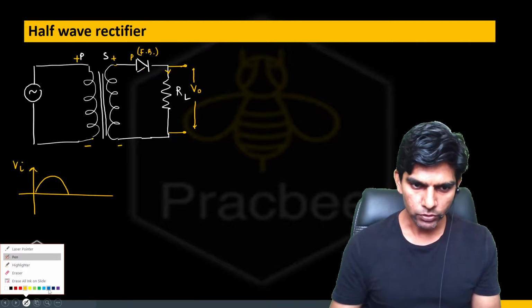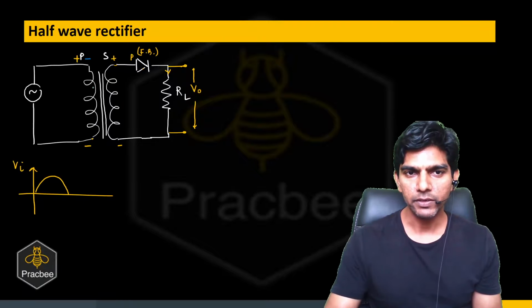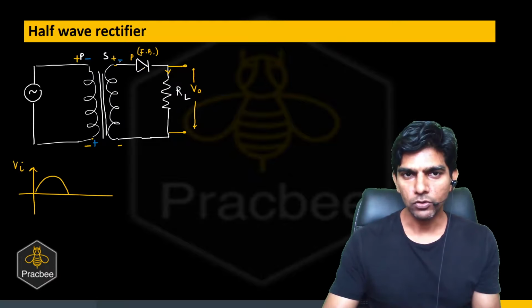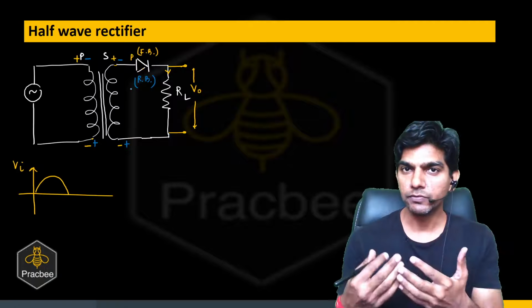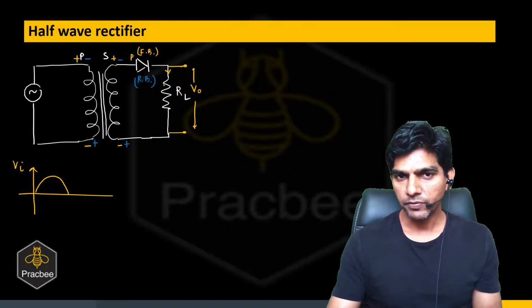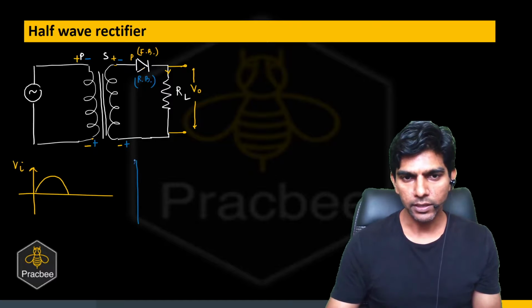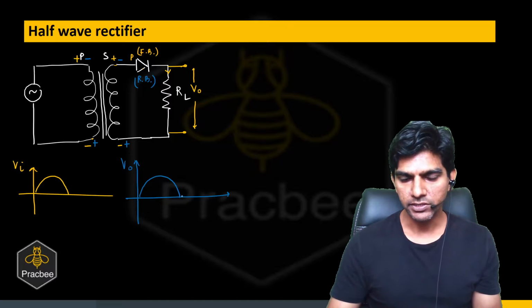Now if you talk about the second half cycle, which is the negative voltage, the top side of the primary will be at low potential, bottom will be at high potential. Similarly, by mutual induction, in the secondary coil the top side will be at low potential and bottom at high potential. In that case, the diode will become reverse biased, so it is non-conducting. We are considering a case of an ideal diode. If it is non-conducting, there will be no current through the load resistor, so there will be no reading. So if I plot the graph for output, it will be like this. For the first half cycle, we'll have some output voltage, and then it will be 0.